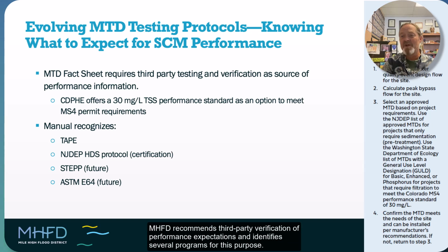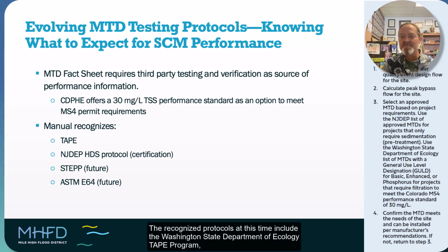MHFD recommends third-party verification of performance expectations and identifies several programs for this purpose. At the time that this MTD fact sheet was prepared, MTD certification protocols are still evolving. The recognized protocols at this time include the Washington State Department of Ecology TAPE program, particularly for filtration-based practices, and the New Jersey Department of Environmental Protection HDS protocol for HDSs.